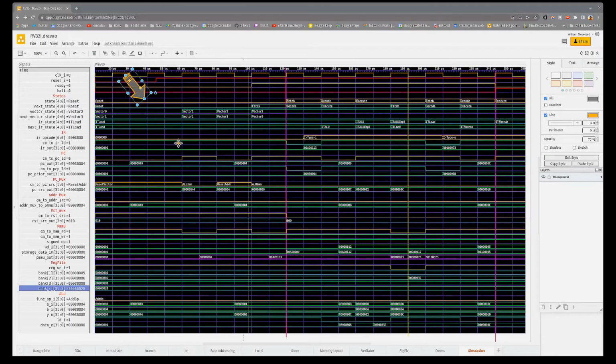Here we are in the simulation, and as always over here to the left side is our reset sequence, but what's different is our X4 register is preloaded with a hex value, 28, and we're going to add 10 to it, or A, and hopefully we get the value 32 out. So if we come over here to the beginning of the fetch sequence for the instruction, we've recognized on the falling edge that it is an I-type immediate instruction, and we pulled it in.